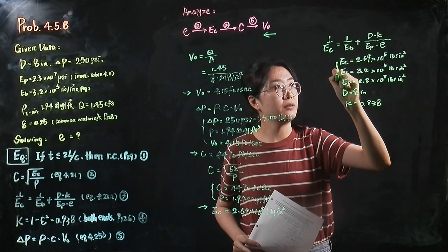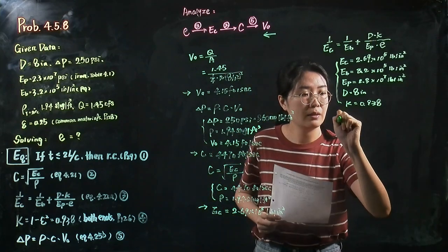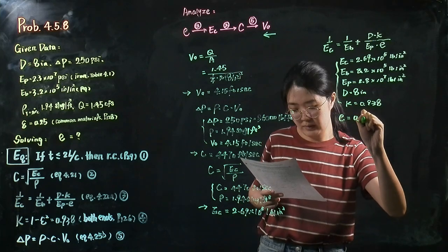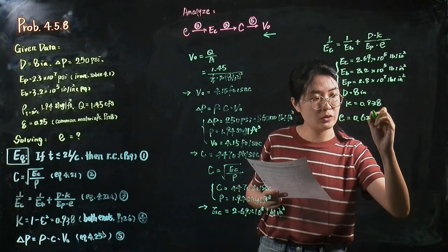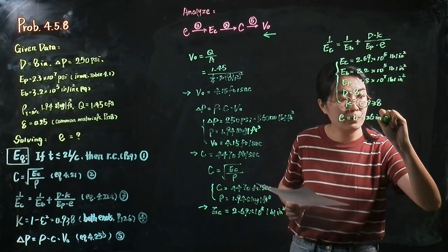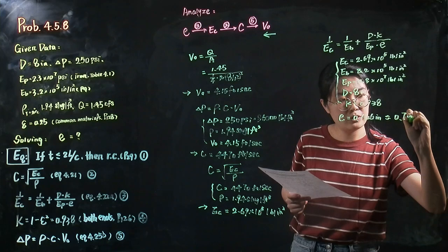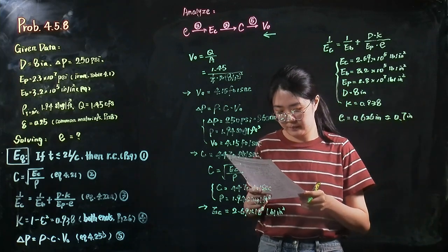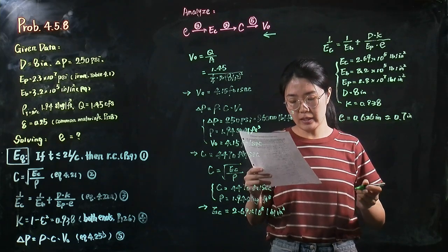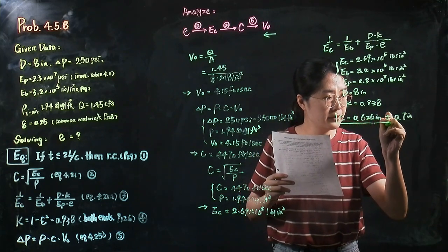If we bring the value back to this equation, we can get the thickness. It equals 0.6626 inch, which is close to 0.7 inch. Therefore, the required pipe thickness to account for any operational pressure should equal 0.7 inch.